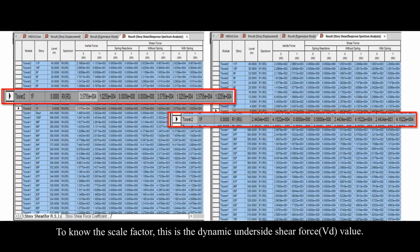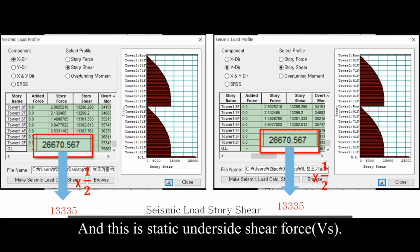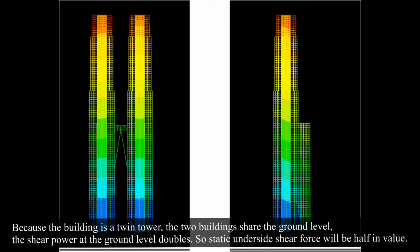To know the scale factor, this is the dynamic underside shear force value. And this is static underside shear force. Because the building is a twin tower, the two buildings share the ground level, the shear force at the ground level doubles. So static underside shear force will be half in value.